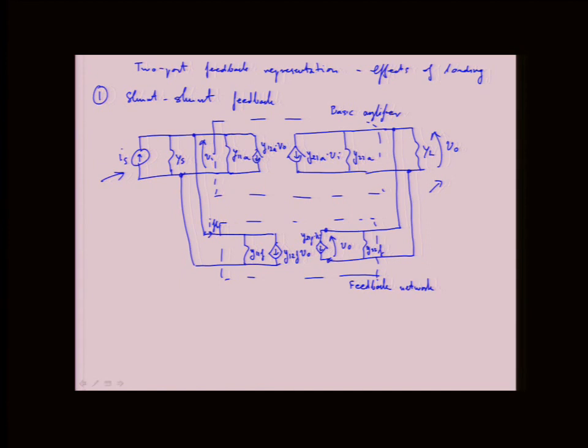So what we do instead is try to do some inspection analysis. One thing to note is the reason we're using these Y-parameter representations, just for review for people who may have forgotten: both the amplifier and the feedback network can be represented through Y-parameter analysis, where I have port 1 and port 2, with V1, I1 and V2, I2. In general, I can write I1 equals Y11 times V1 plus Y12 times V2, and I2 equals Y21 times V1 plus Y22 times V2.